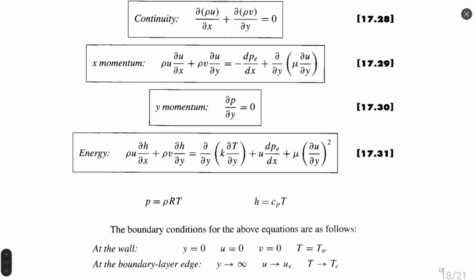You can see that it's a bidimensional case. We have only x and y direction. It's a stationary case. We do not have time derivative. And the continuity equation, the first, equation 28, remains the same for external flow and flow inside boundary layer, because we have conservation of mass always working. Cannot simplify anything inside mass conservation.